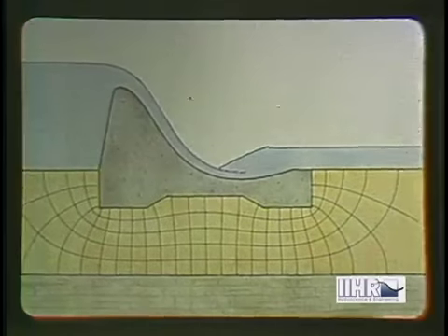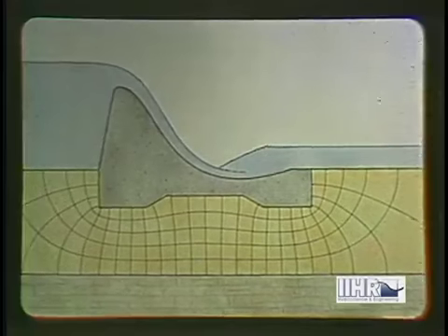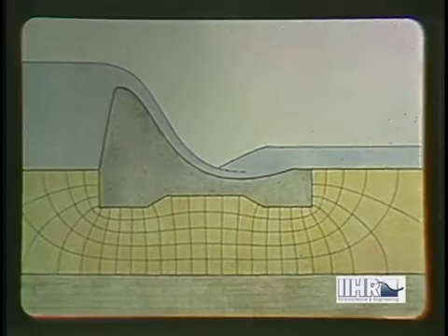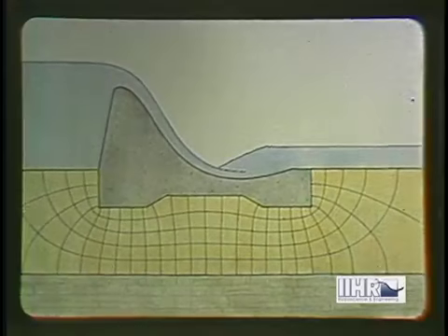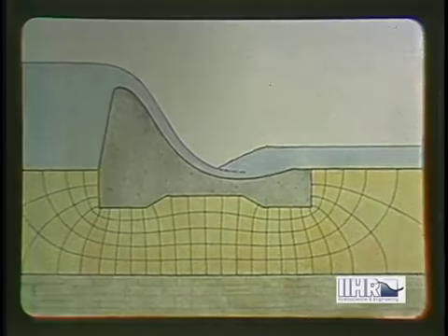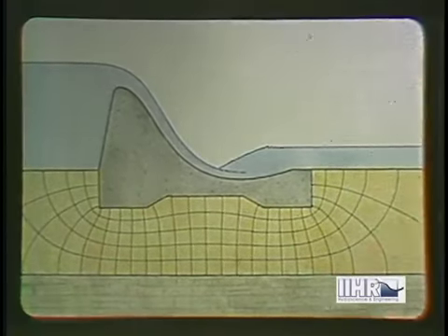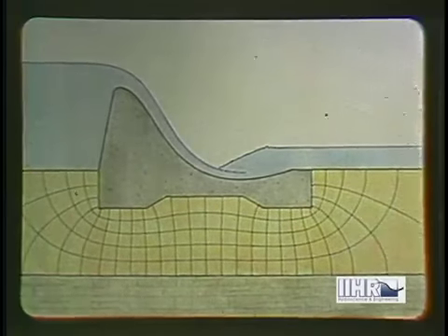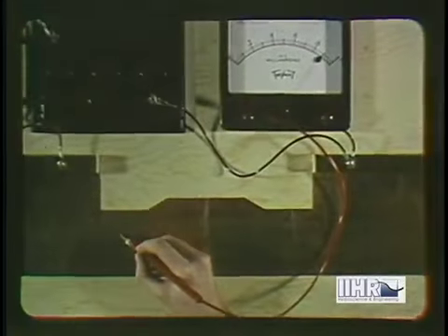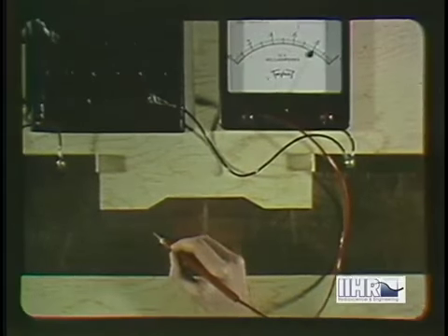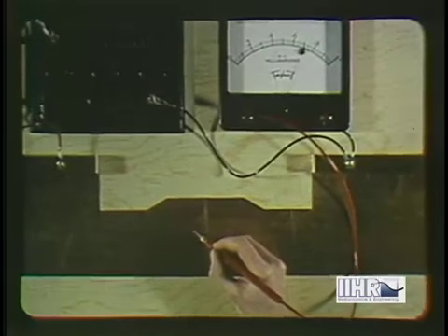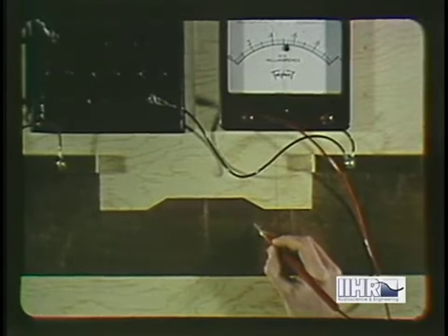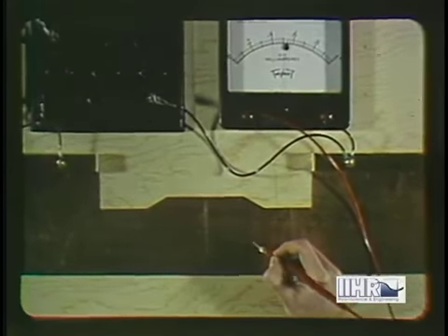It is of interest to note that the percolation of either a liquid or a gas through a permeable material, like the earth below a dam, will also be indicated by a flow net if the material is of the same porosity in all directions at all points. Moreover, the same net will correspond to the flow of an electrical current through a conductor, the voltage varying at a maximum rate along a streamline, but remaining constant along a normal line.